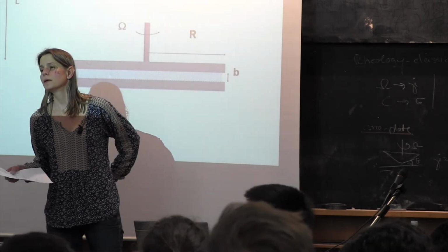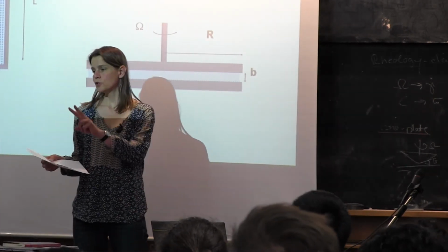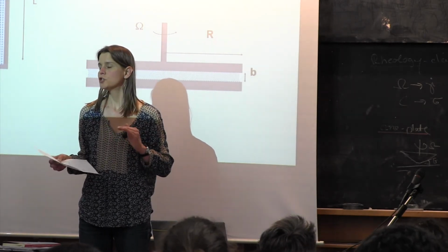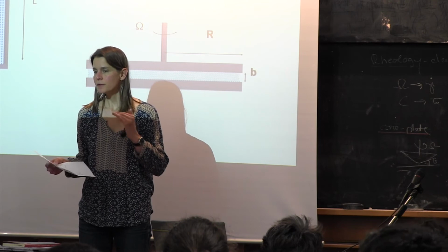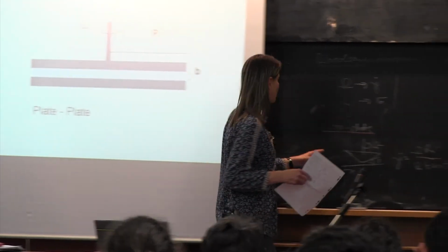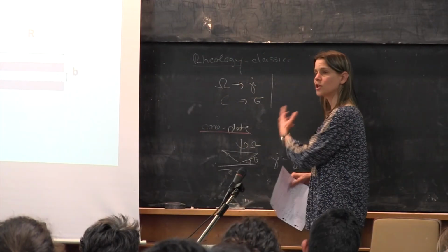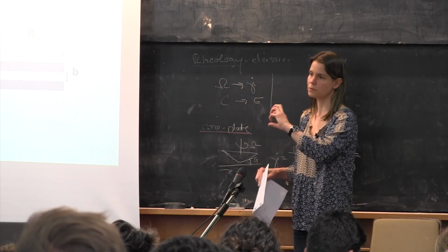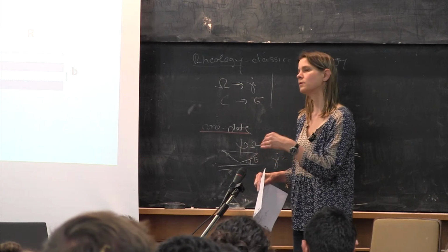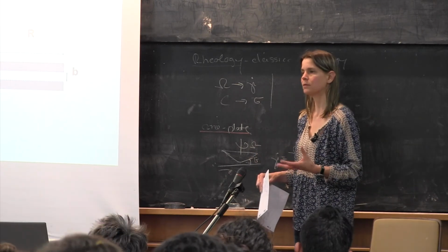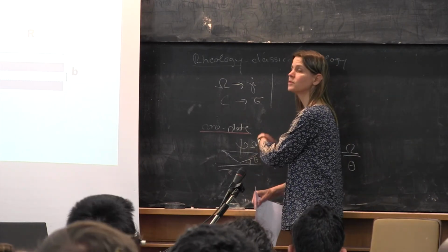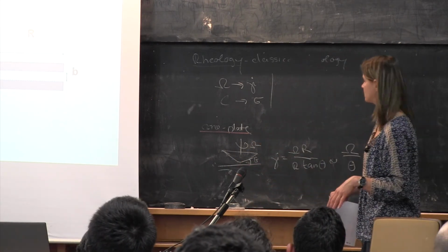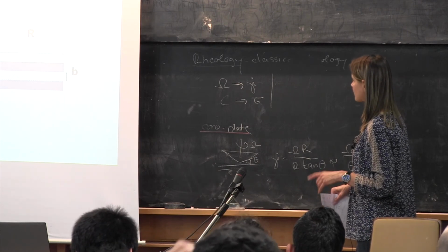It's convenient to use the cone plate geometry because the two geometries that I just introduced have the advantage that they have a constant shear rate. There are other types of geometries. So if you would not have a cone here but a plate, then your shear rate is not constant. And as we know that non-Newtonian fluids interact with the shear rate, this makes your measurement more ambiguous. So if you can work in a geometry with a constant shear rate, it's much better. So it's two very different ways of introducing this. So one remark,